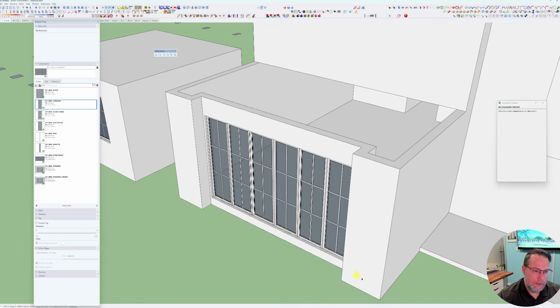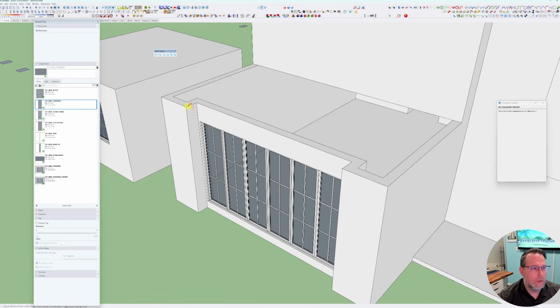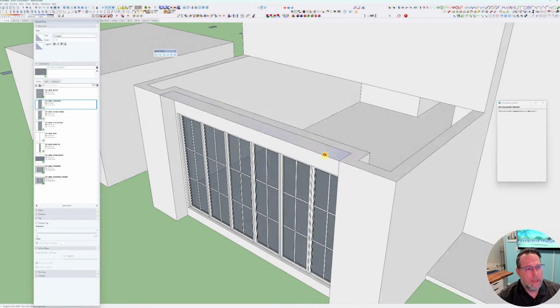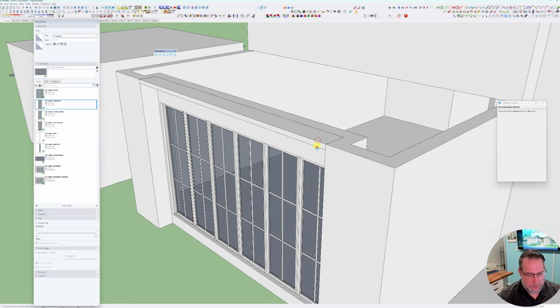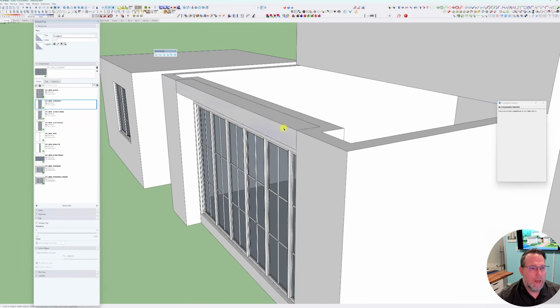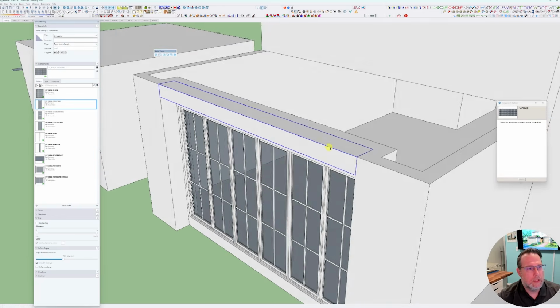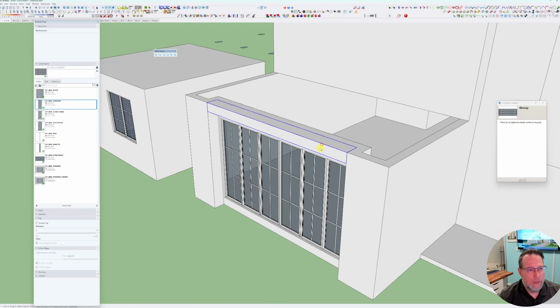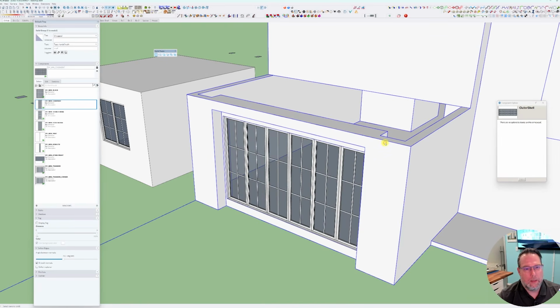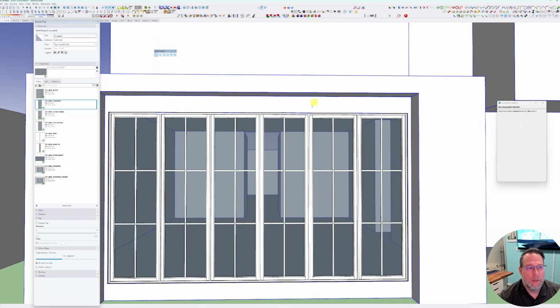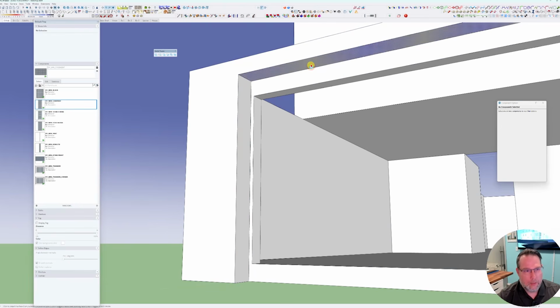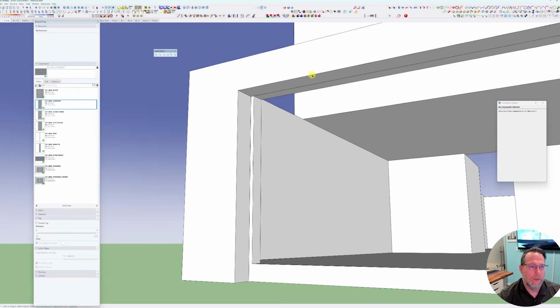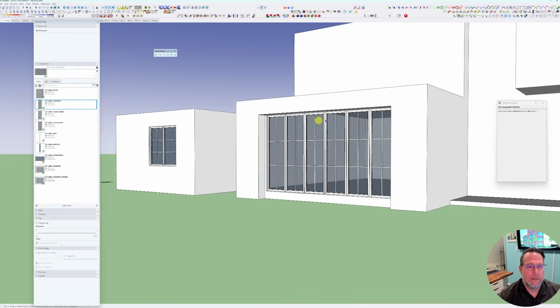And you can see this recess that I've created where this window goes, because in this one I actually want to create kind of an exterior soffit, if you will. So I'm going to push this down 12 inches, triple click this, Control G to turn that into a group. So now I have my wall group and I have my soffit group. And if I hit Alt C and join those two together, I have now created that. Maybe I want this soffit down another bit to really clean this up, and we can do that.